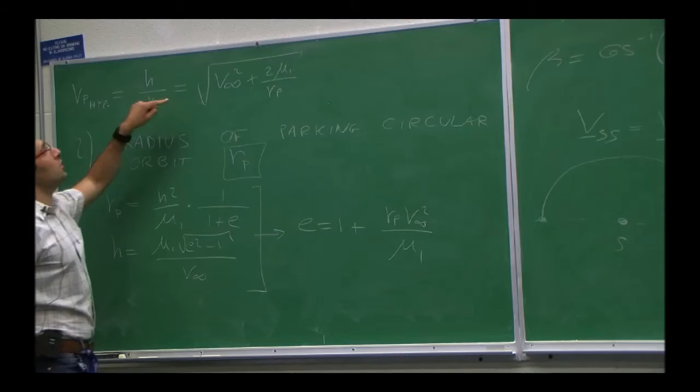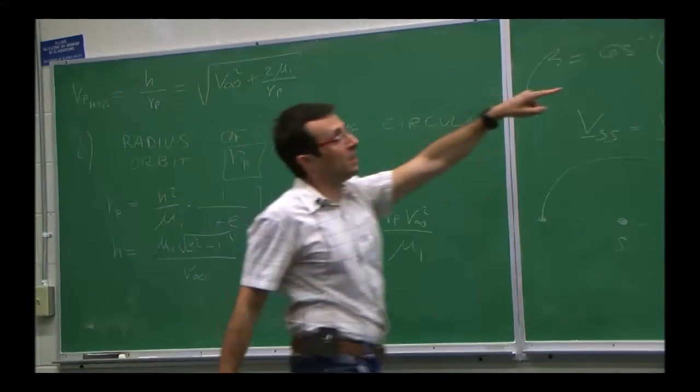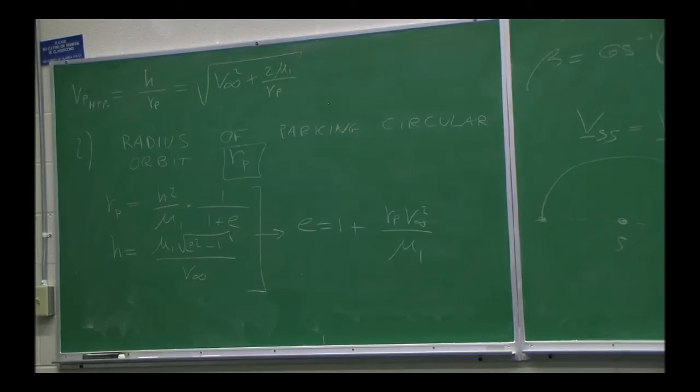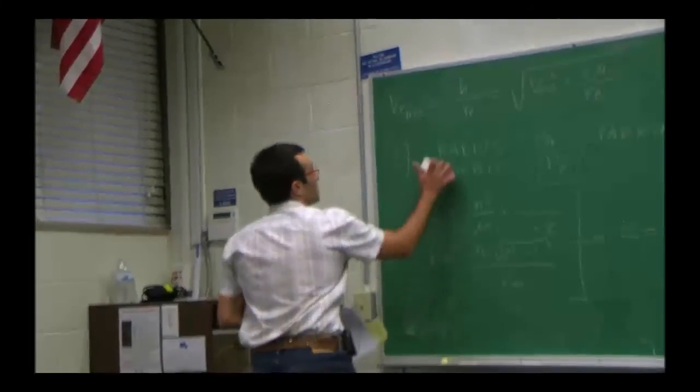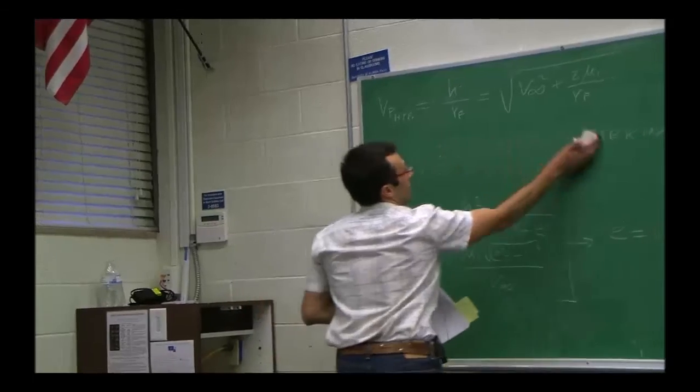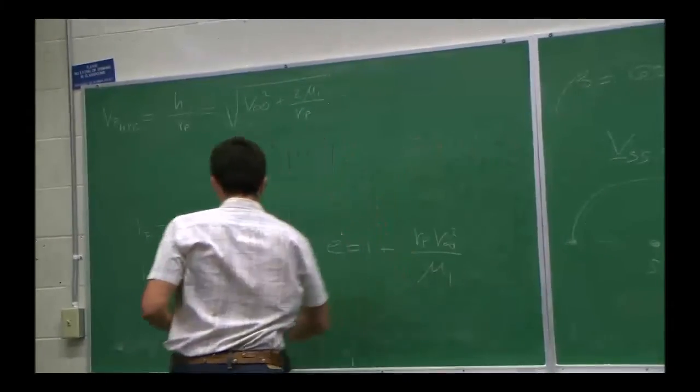So this is the velocity you need to have at that point P at the perigee to be on the correct hyperbolic path. So your real delta V, the actual maneuver that you are going to do, is not up there at the edge of the sphere of influence. It's actually at the perigee, and the delta V, it's simply what?